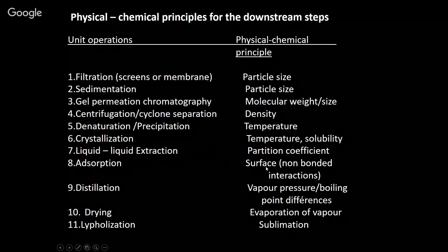Then comes adsorption. This is a surface phenomenon. We have gases getting adsorbed on solids. Generally adsorption is not used too much in bioprocess, but of course it's used when you're venting out gases. If you have any toxic gases, you can remove them by using activated carbon, silica, zeolite, alumina, and so on.